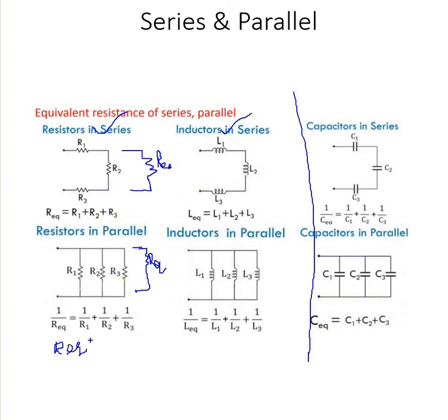You will find out and write the answers. Similarly, inductance is also similar. But when you go for the capacitor, it is reversed. Reverse means series connected uses this formula, and if it is a parallel connection of the capacitance, use this formula. What is this formula? Addition. So I add C1, C2, C3.